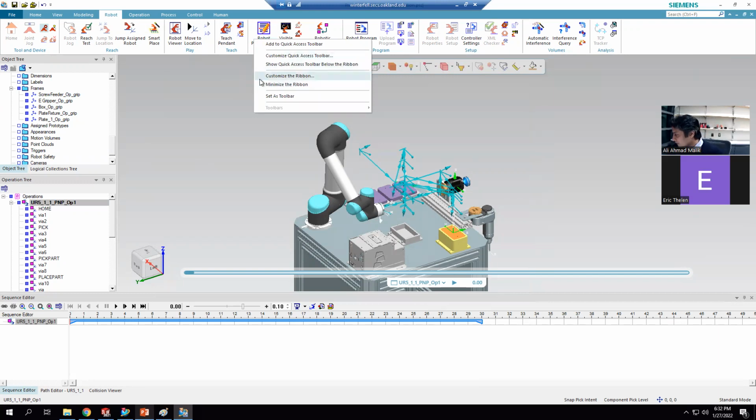You can test it as well. This is not something that you have to do. I am just telling you that if someone is excited to experiment with how the program can be downloaded to the robot, you can download the TeachPendant of the UR robot on your computer. It is downloadable from the UR robot website. There is some name for it, but they have only one software on their website. So basically, you get the complete robot controller on your computer, and then you can generate the file and download it to that robot controller. It will still be a simulation kind of thing, but you will be able to see how the same program behaves in the actual robot controller.